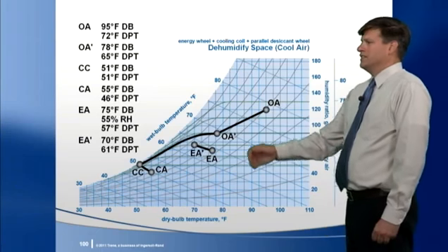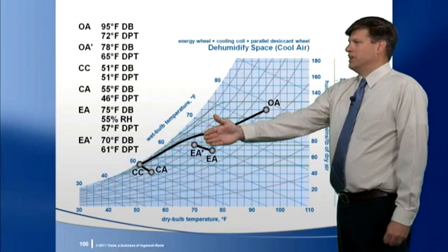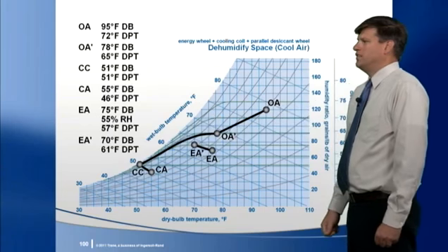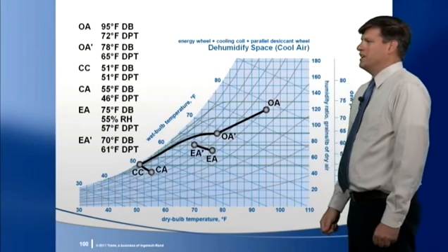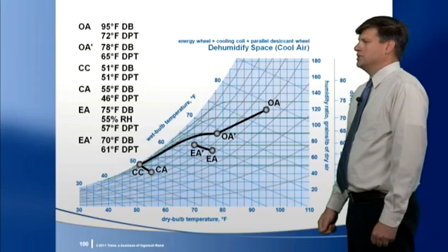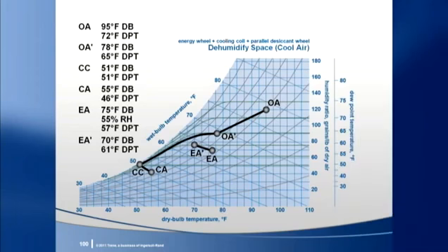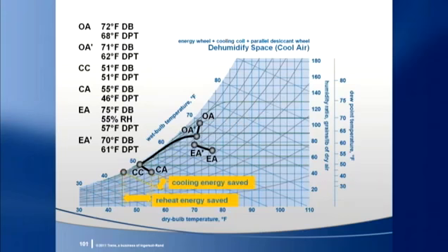On the other side, the exhaust air regenerates the desiccant, which cools and humidifies the air. This air then passes through the exhaust side of the energy wheel. The pre-cooling of the exhaust improves the sensible cooling benefit of the energy wheel, but since the desiccant wheel added moisture to the exhaust air, the dehumidification benefit of the energy wheel is lessened. Since the condition of the exhaust air remains relatively constant year-round, the benefit of the downstream desiccant wheel will remain relatively constant.